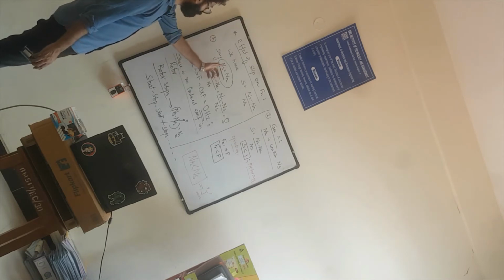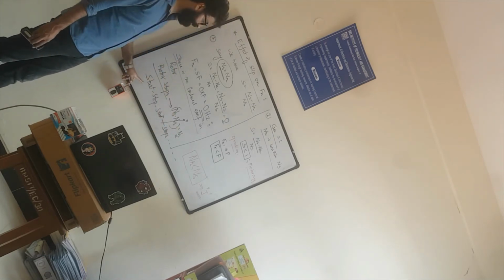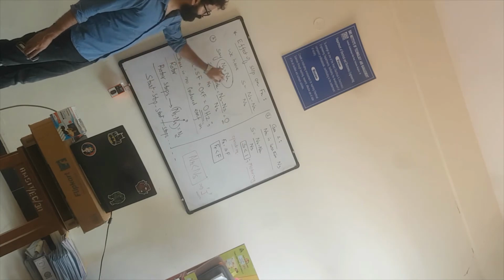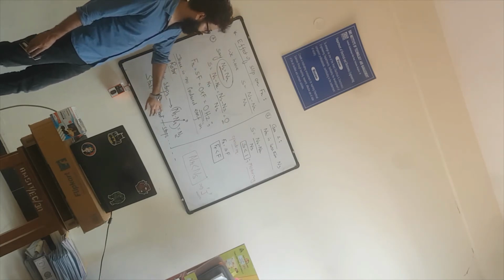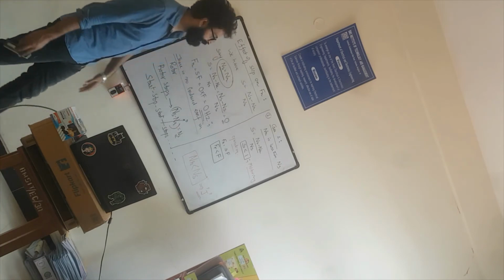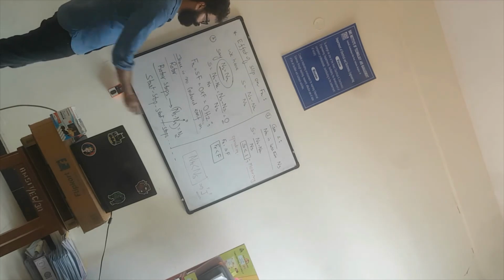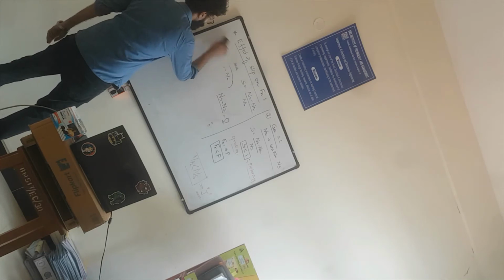What if the rotor speed is equal to the stator speed? What happens? Frequency becomes 0, due to which the rotor stops. The moment the rotor stops, there will be a relative speed, and due to the relative speed, the motor once again starts. Once again, when it reaches synchronous speed, it stops, then starts, and then stops. Highly objectionable operation, but due to the moment of inertia, luckily we are not seeing this particular behavior in our day-to-day life. That's because every motor will have some amount of moment of inertia.